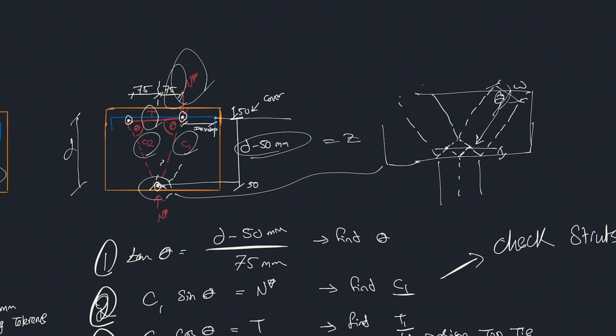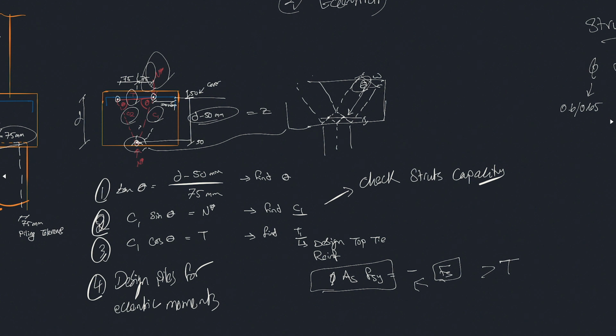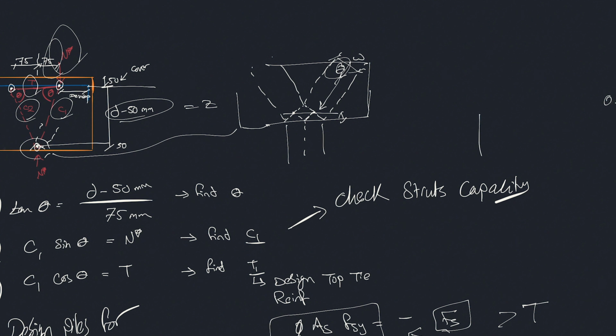And then the last thing is this eccentricity externally between the column and the pile. You have to make sure that you specify this moment on the pile, because at the end of the day, what we're really doing is saying we have a point here, we have a point here, and somehow the loads get transferred through the pile cap. So if you really think about it, this one here needs to be fixed, and there needs to be a moment, and basically this moment is the load of the column times the eccentricity, where the allowable tolerance is about 75 mil for piling.